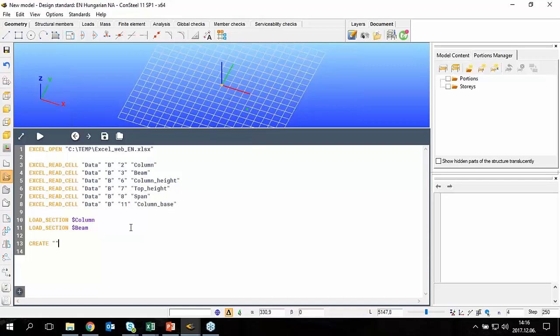I have to give an ID for this structural member, which is an optional parameter. If you would check on the wiki, you would see that it is optional. It is optional because if you want to place any, for example, a point load later on in your script to a specified structural member, you have to know what the member is on which you want to place the load. So this is how you define it, of course, with an ID.